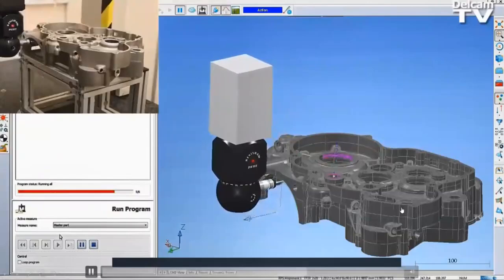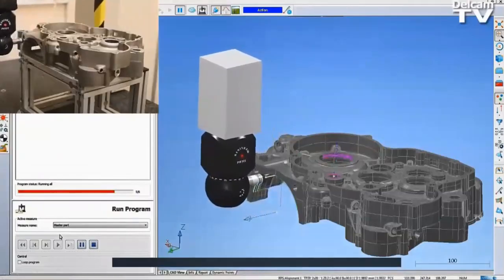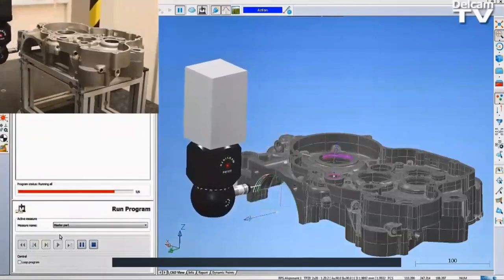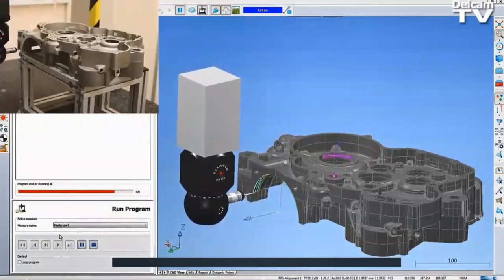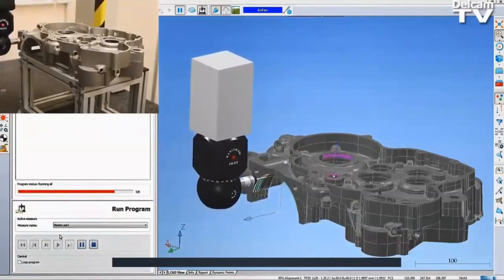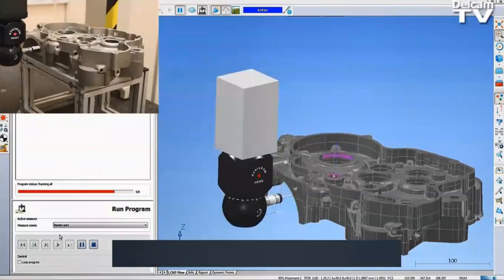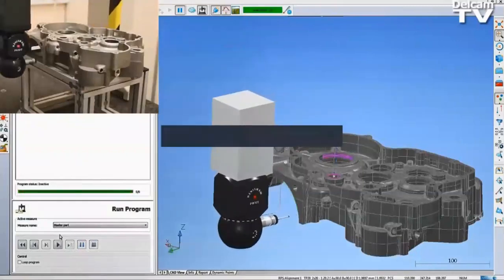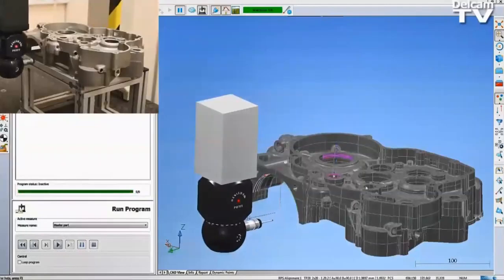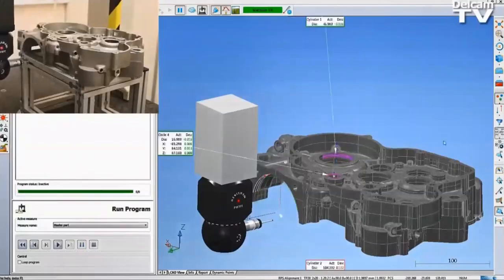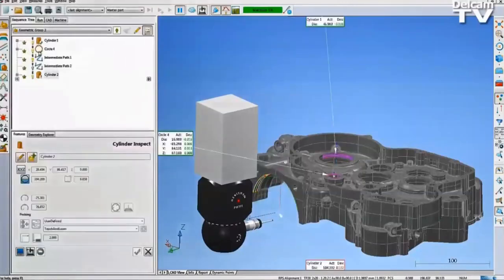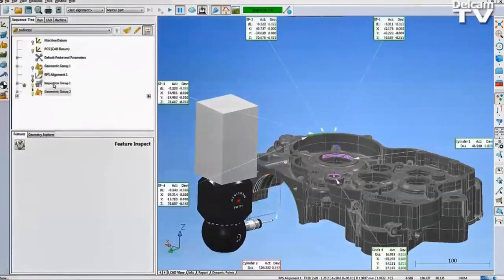Here you can see one thing. Inside the CNC CMM, if you have the Renishaw PH10 probe, you can do the 3-axis inspection as well as 5-axis positional inspection. After this, we can display the labels to show the areas that have been inspected. So this is the way you can inspect your component inside the CNC CMM.